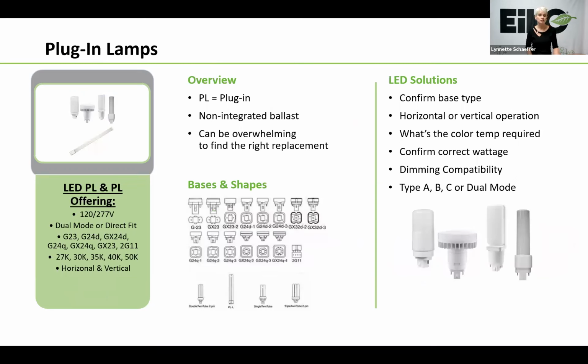Now, PL lamps, which stands for plug-in, these fluorescent lamps plug into a ballast. Now, due to the various bases and shapes, it can be very overwhelming to find the right LED replacement because you need to know if the existing base is a 2-pin, a 4-pin, is it a GU23, a GX23, all of that plays into effect.